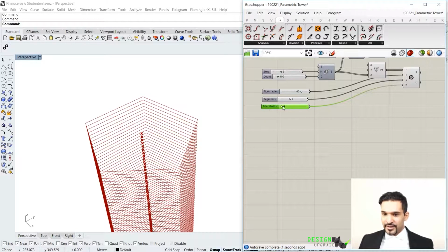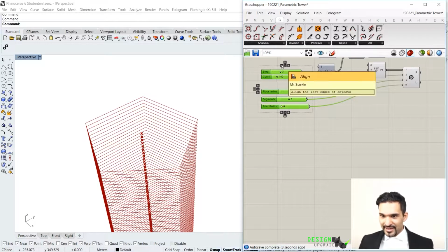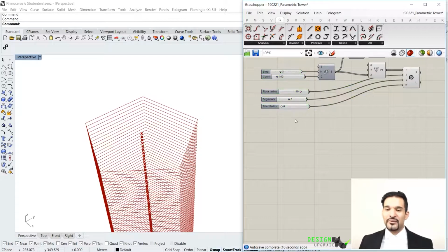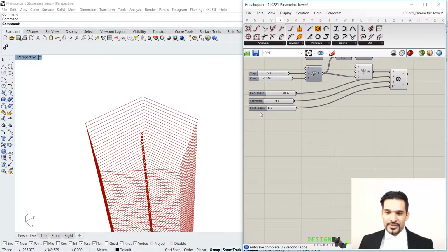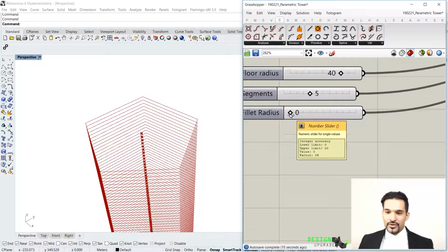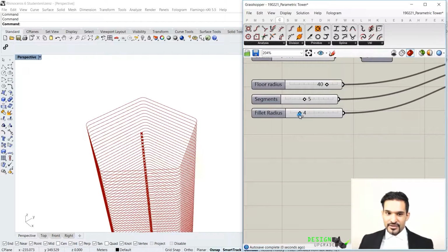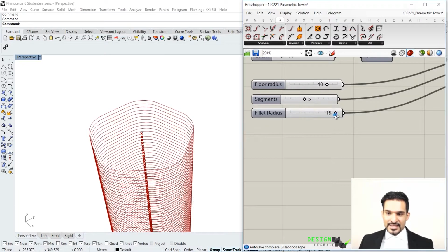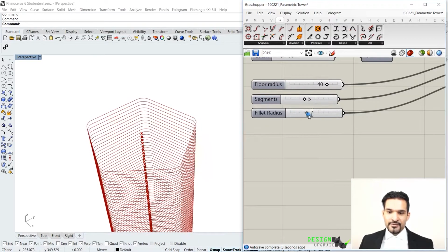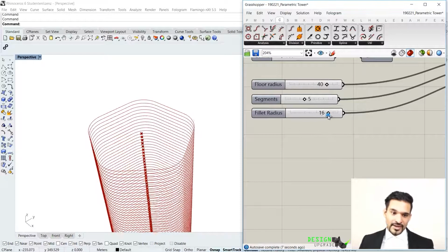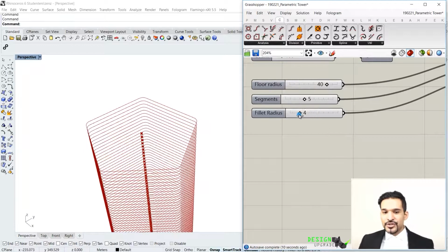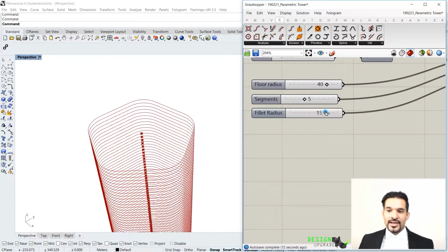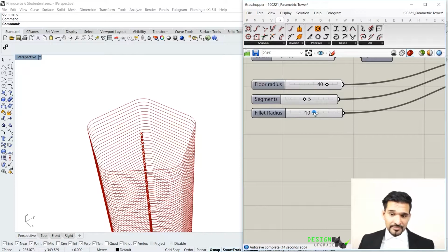It will now say fillet radius, which is good. I take off my sliders and you will get these widgets here. You can just press on this guy, which will align them. If you want to already start aligning your sliders, you can do it so. And if I now go to the slider and just start to crank up my values, you can see how this form has been filleted at the corners, right? And this is a very nice feature which you can then basically control and use to alter your shape. Let's leave it at 10, the radius 10 right now.